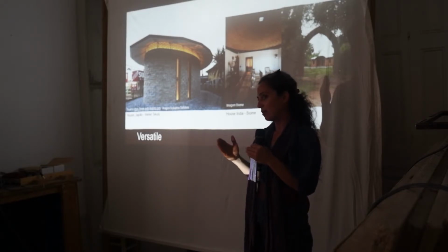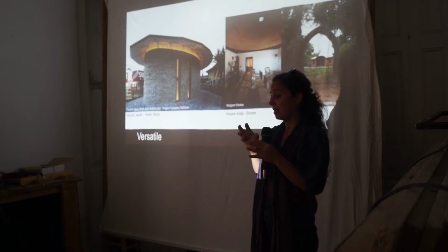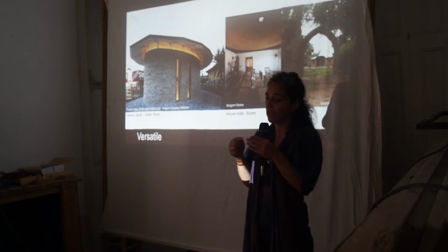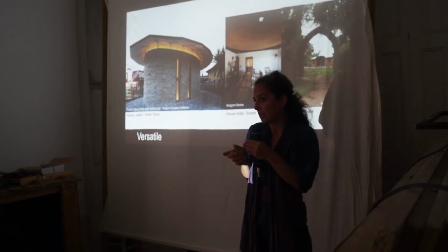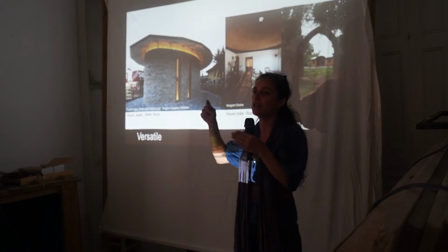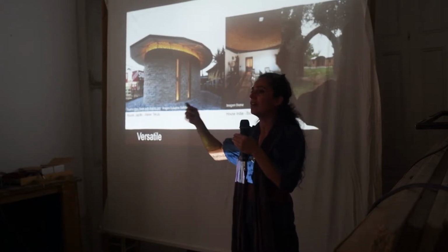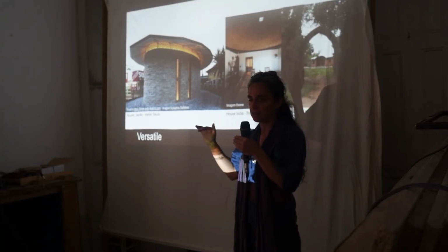The people that work with concrete mixed with earth, what happens is you need a specific kind of earth. So if you don't have that skeleton in the earth, you have to change it a little bit. But it's very important, don't ever go more than 7% of cement. If you go above that, it's no longer sustainable. It's no longer earth construction.